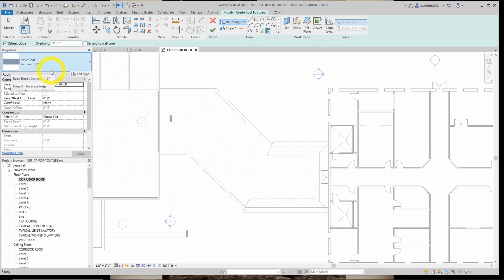And we're going to pay close attention to the picture on page 344. We're going to make sure the line matches to the roof on the right. So we're mostly going to use the draw panel and the pick lines command instead of pick walls. Make sure the overhang is 1, as it should be.